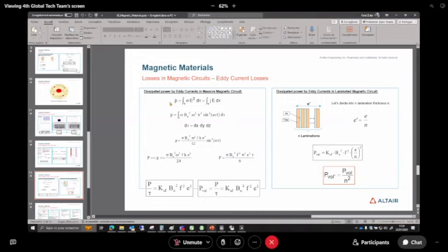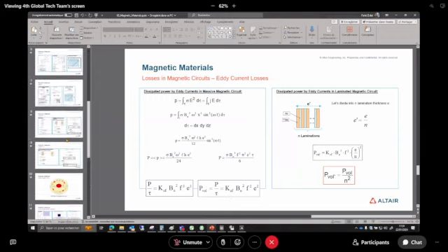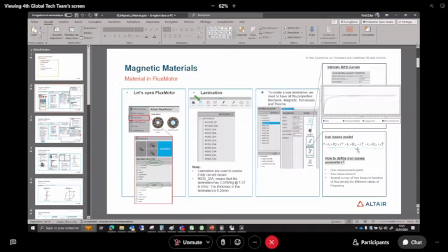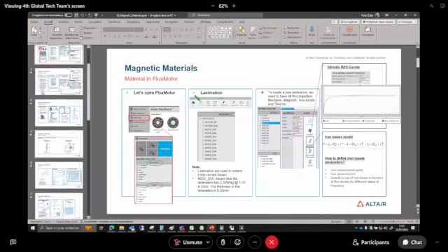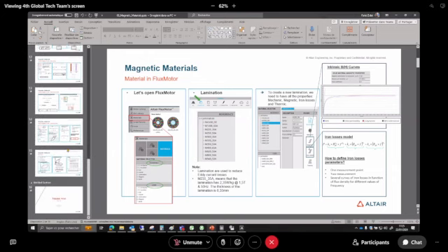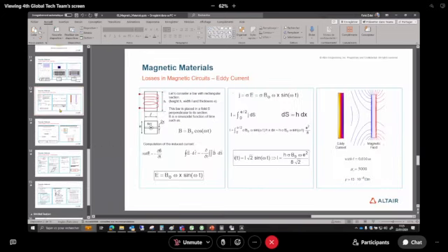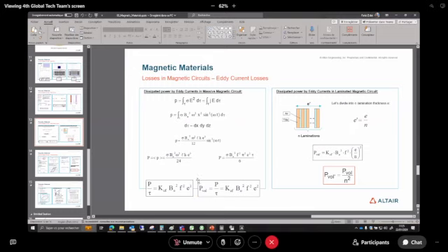Here the losses can be computed like this. At the end of the development, we can see that the losses for the volume can be written as a factor. This is one factor of Bertotti losses. And actually, this is one part of Bertotti losses, if I come back to my model here, which are the classical losses, right? So this is one part of the losses on the block.